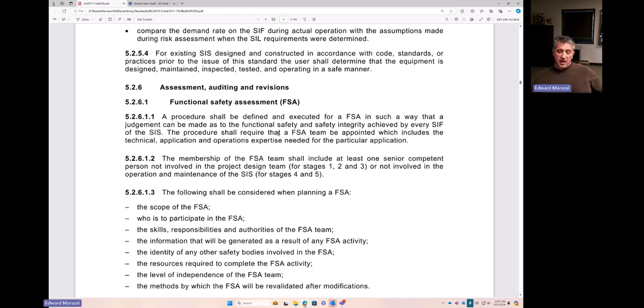One of the upcoming webinars that I need to get on the calendar is going to talk about why it's a really bad idea to try to account for human failure when you're doing your SIL verification calculations. Long story short, it's not only not beneficial, it's going to cause you to have worse designs.